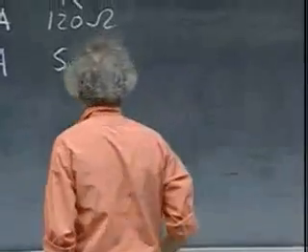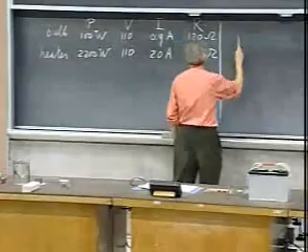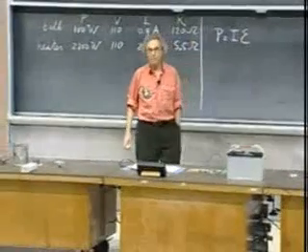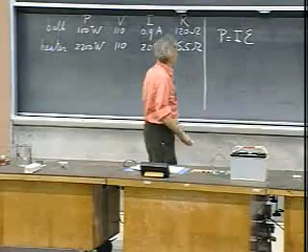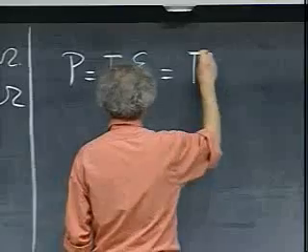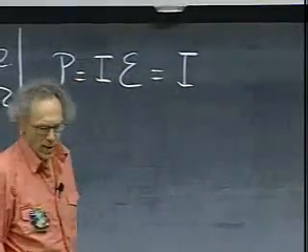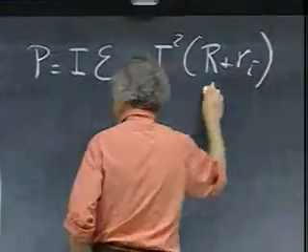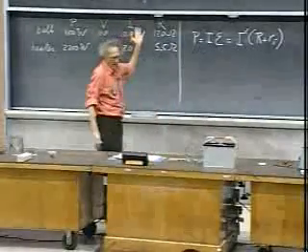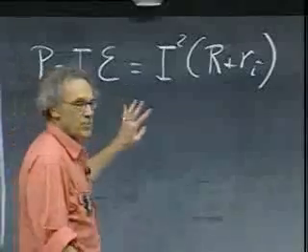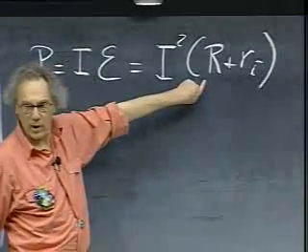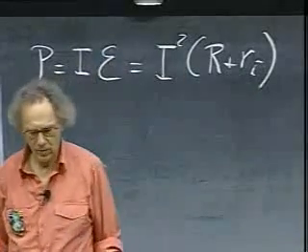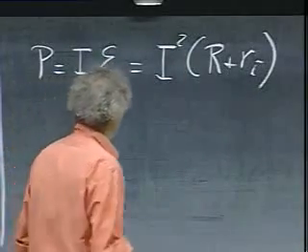The power delivered by a battery is the current that the battery delivers times E, which is this EMF. And so when the current is running, it is I squared times the sum of the two resistances. The external one plus the internal one. You can never bypass that. The heat that is produced in the external one is I square capital R, but the heat that is produced inside the battery is I square little r. You can't avoid that.